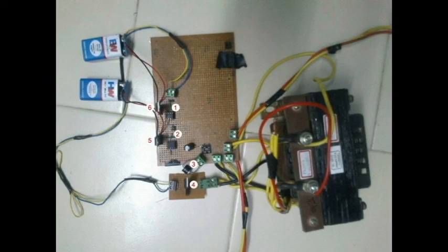The screen shows the hardware implementation of a buck-boost converter. The various ICs used to implement the circuit are marked. The ones marked in red color are ICs manufactured by TI. This board uses 4 TI ICs, namely UA7808, UA7805, CSD18504KCS, and UCC37322P. The optocoupler IC is manufactured by Fairchild.